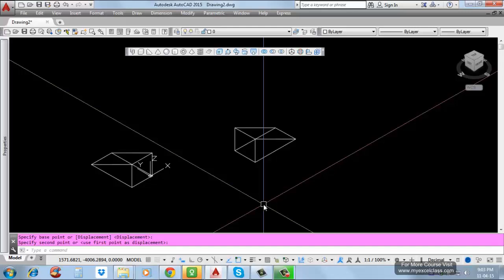That is another option. Suppose you don't want to change your UCS, you can keep your UCS as it is, because the coordinates from objects or projects will be these. It cannot be rotated, because if you rotate it, the x and y dimensions you are giving will change. So we will keep the UCS the same, and after making this wedge we can rotate it up to our requirement.